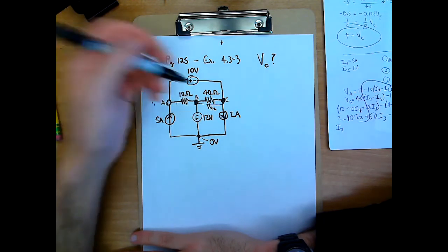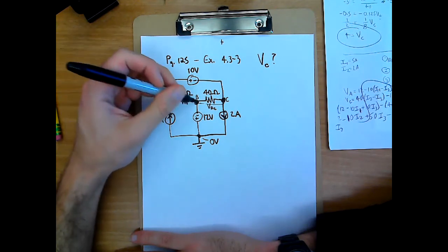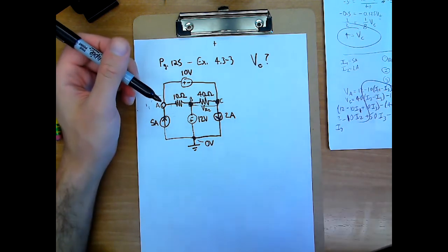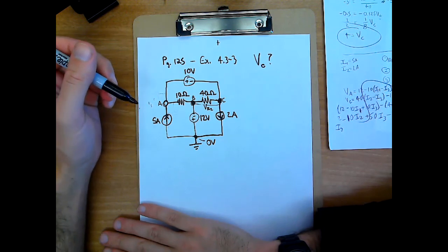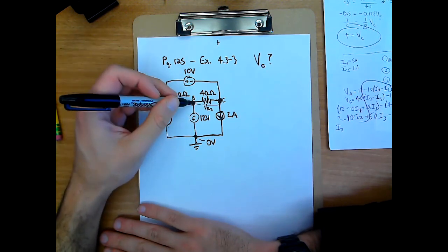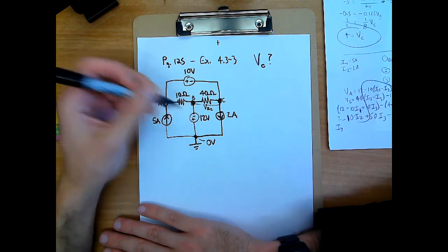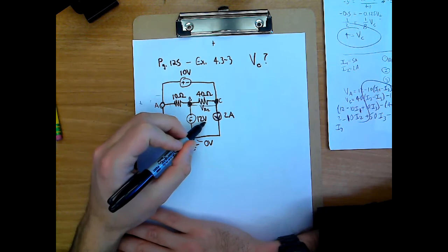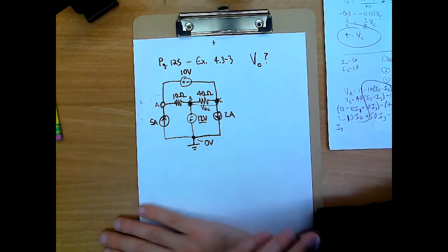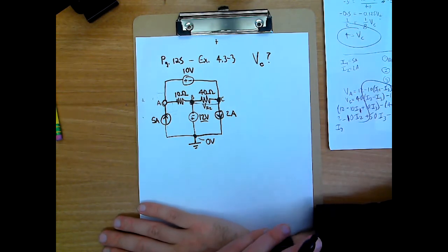For doing the node voltage method, it means that we're trying to express the currents going into each node as a function of voltage, right? So a couple of things that I can tell: one is that the node voltage at B would be what? Negative 12 volts. I can say that because this voltage source is specified as being a positive 12 volt source.